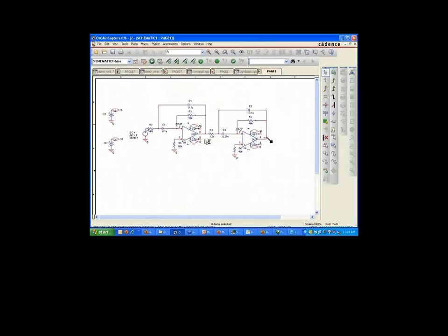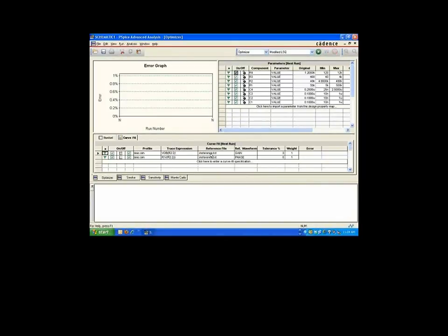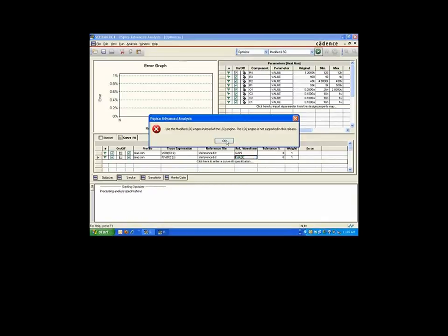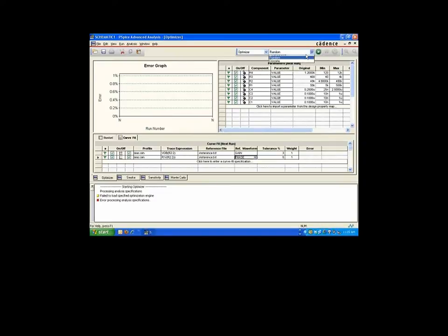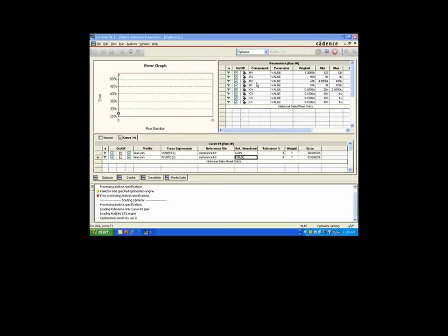And what I've done is I've taken those outputs and mapped them to that text file. I've done that ahead of time. So the text file is right here. The gain column is matched to my gain measurement, and the same reference file, the phase column, is matched to my phase measurement. And I'm telling it you can change anything in the design, so all those different components you can go through and change. I'm just matching it to a 3 and a 5% tolerance. So it's not extremely tight, but it's hopefully tight enough to see the capabilities of the tool.